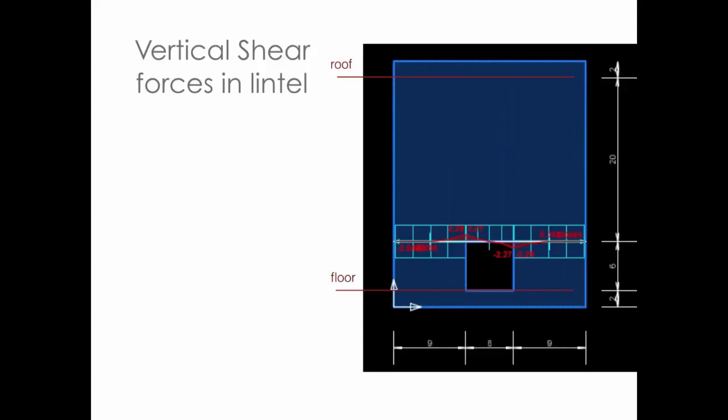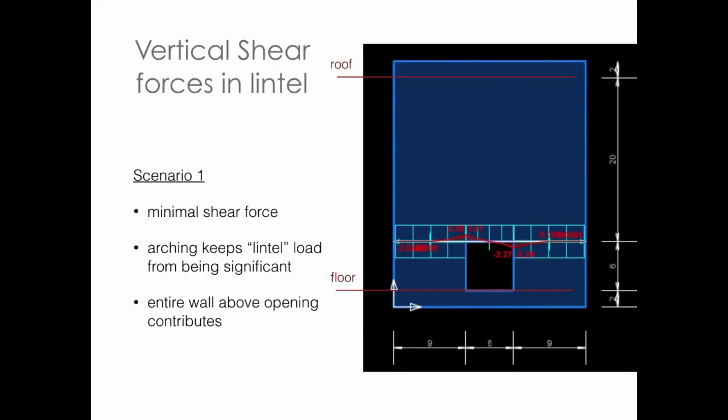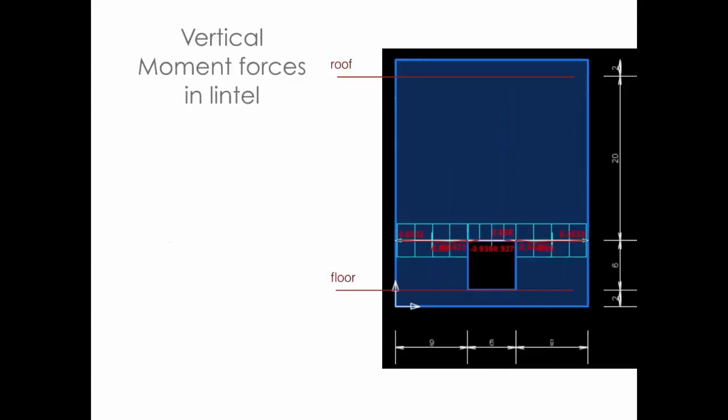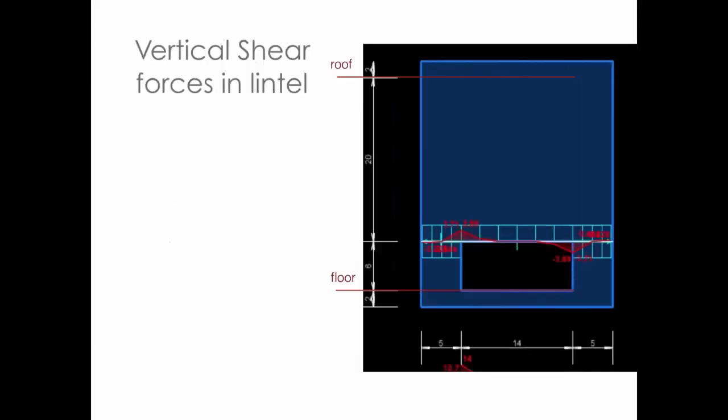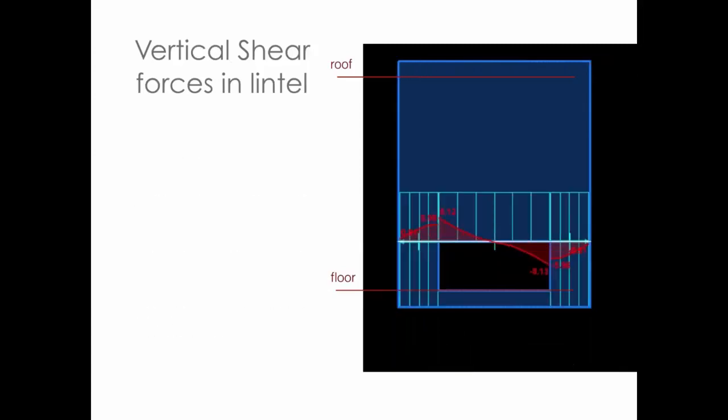Shear within the actual wall, you can see that it's pretty low. And I'm going to give some comparisons here in just a second. Or moments are just about nothing. Moments are just about nothing when I have a finite element analysis and that span over the opening, because there's so much arching going on, shallow, deep arches. It's really distributing that load out, and there's very little actual bending moment within the actual design. Even with the longer span openings, the moments are a fraction of what they would be versus if I would just have a simply supported element, right?